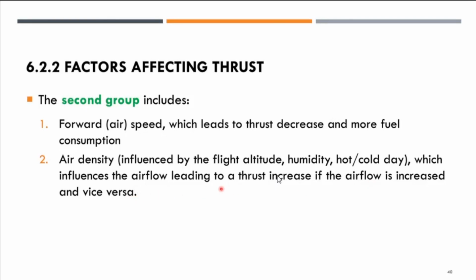So that's why you can see in certain airports, at certain hours there are so many aircraft flying, very busy, and in other situations there are very few aircraft flying. This is also resulted from the consideration of air density. Hot air has less density. Cold air, on a cold day, has higher density. So it will affect the thrust.